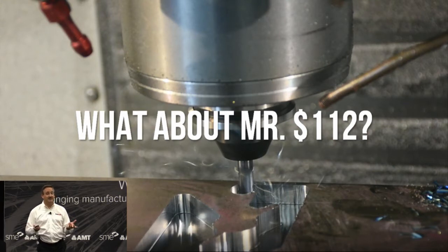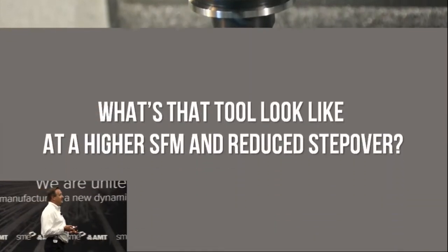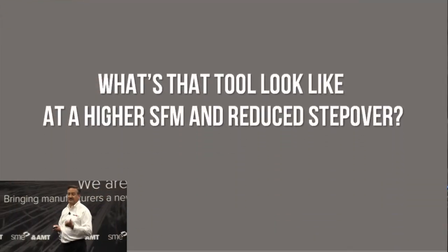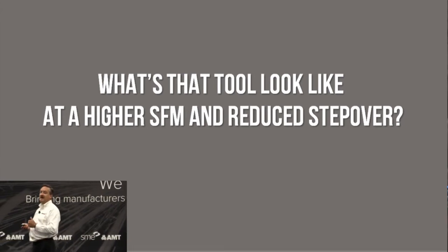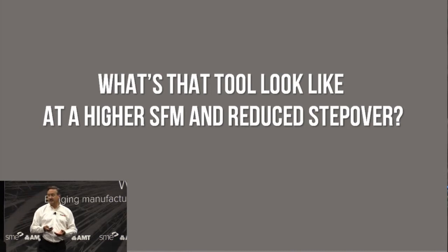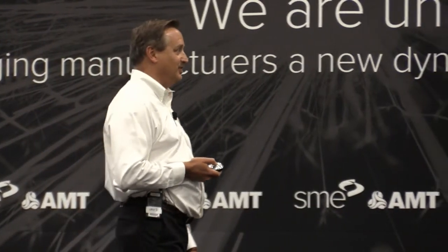And we don't even have to bump it up a lot. What if we were to change the parameters on that? What does it look like if I bump up the surface footage, because I can, as long as I drop down my step over? If I drop down my step over, I need to increase some of the RPM, which in turn is going to get me into material a lot faster from an inch per minute range, right? If I bump that up, now what kind of effect does it have on tool cost?